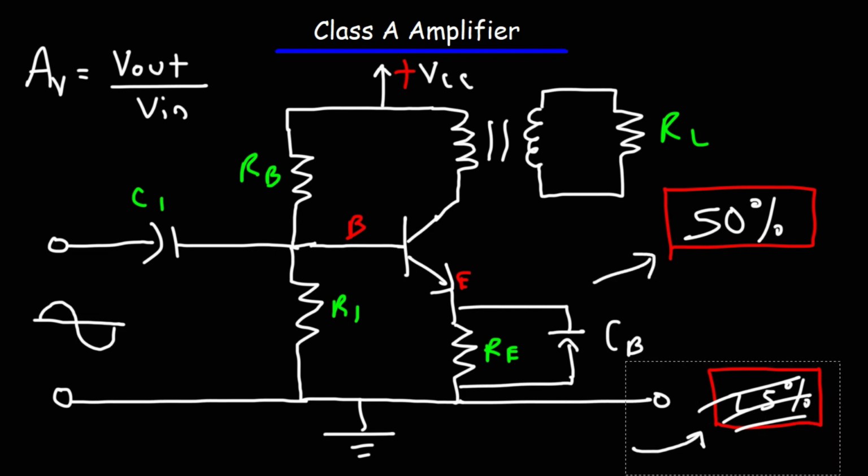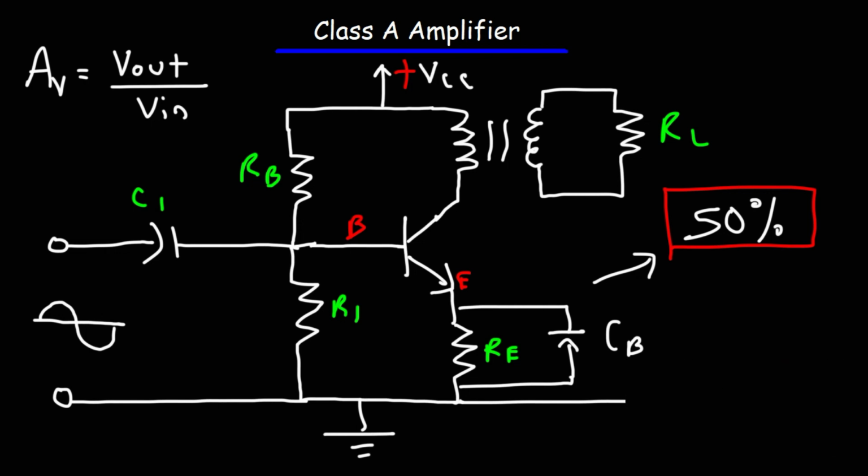Now, here's a question for you. Why is it that replacing RC with a transformer increases the efficiency of the circuit? It has to do with the fact that the transformer, like an inductor, can absorb and release stored energy using its magnetic fields.